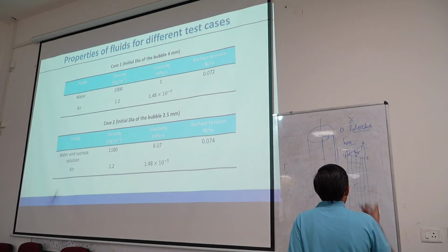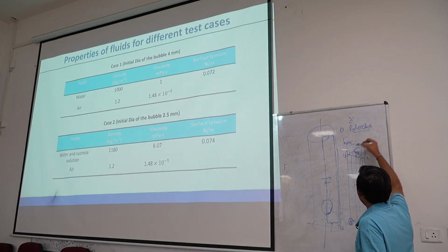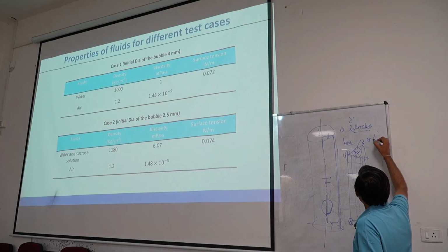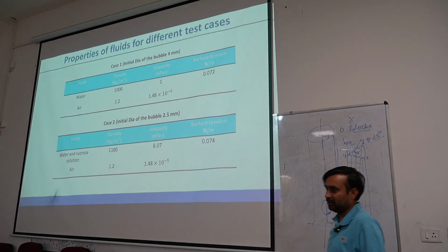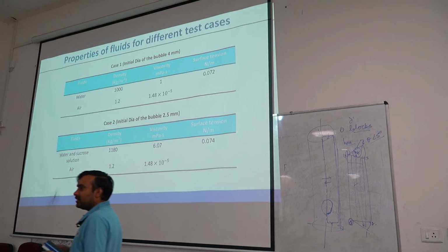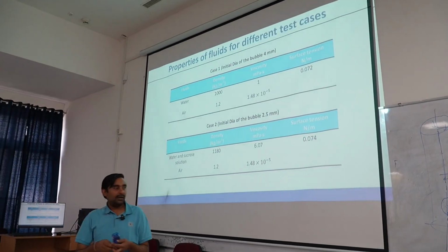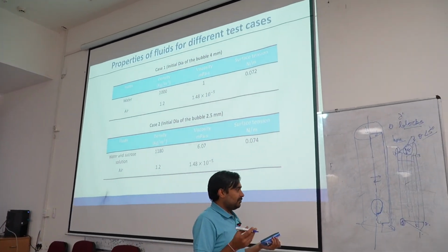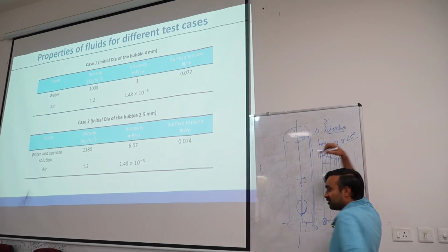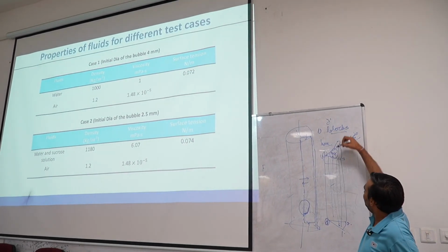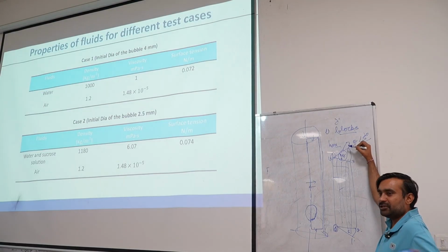Along with that, typically when a wedge is created, the value of theta is kept less than 5 degrees when we are doing axisymmetric simulation. But we also have to tell our solver, because in certain cases we may need to do a simulation over a full wedge.